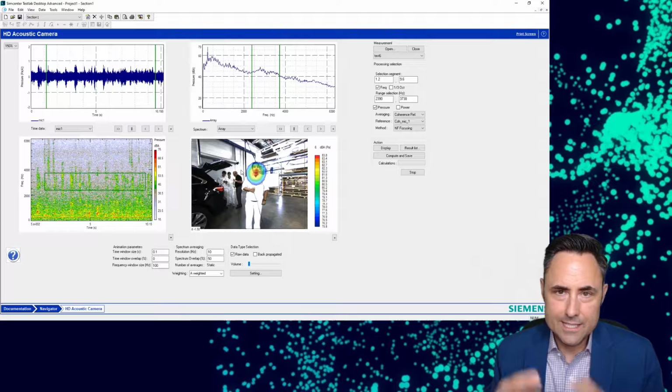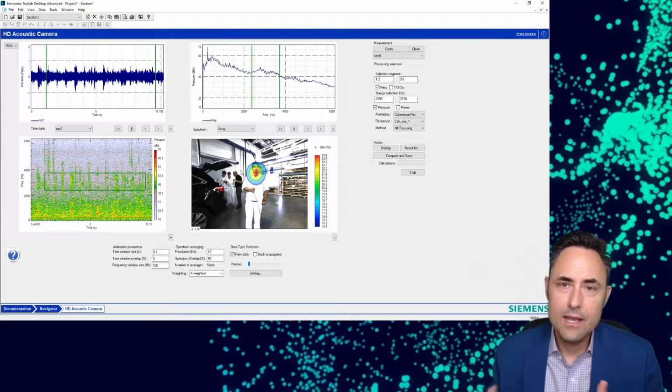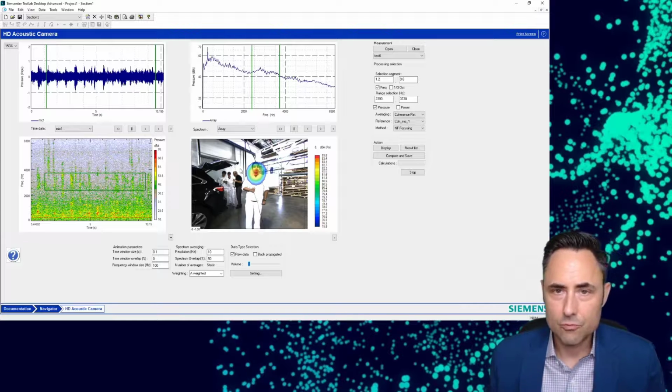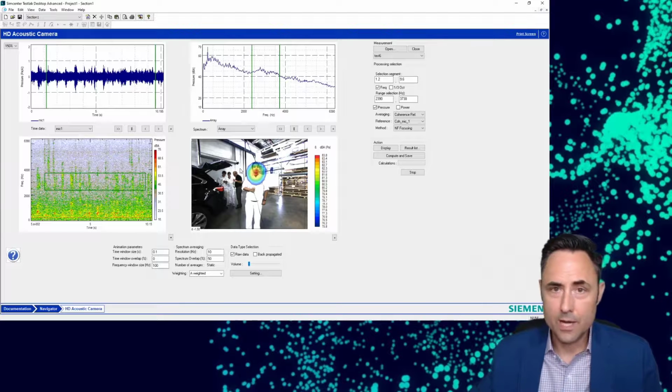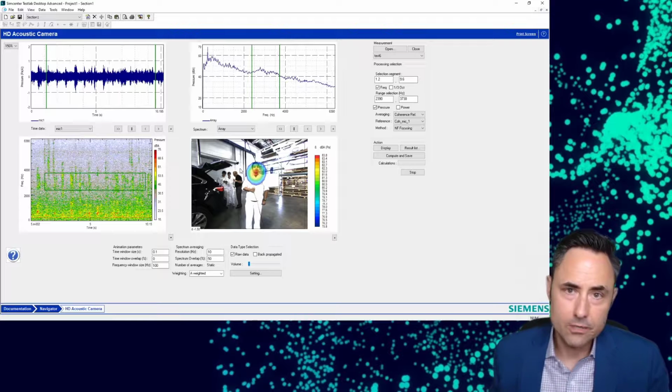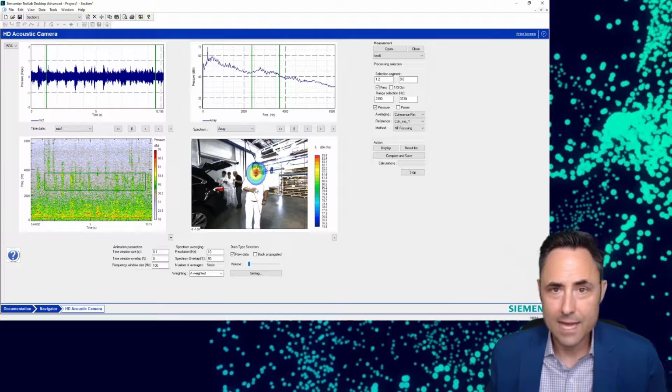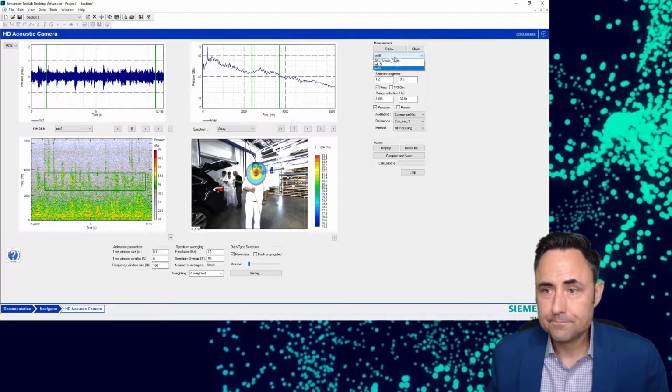Okay, so I can separate sound sources making the same exact frequency content and be able to separate them due to this coherent relationship. It makes it really helpful to identify, say, is our wind noise inside our car coming from, you know, the wiper or from the wind seal leak that I have in the A-pillar. I can separate those two by adding an additional microphone and providing it some sort of coherent relationship. Okay, so that's one application.